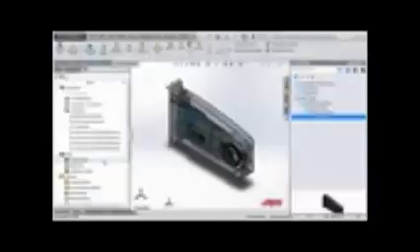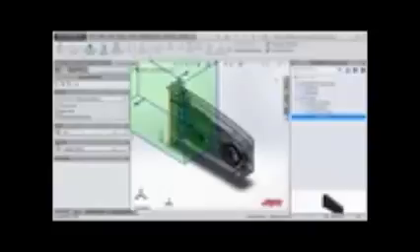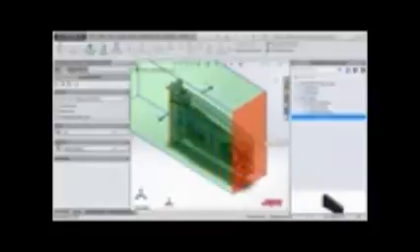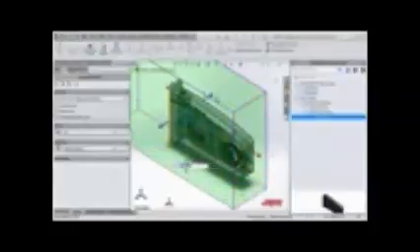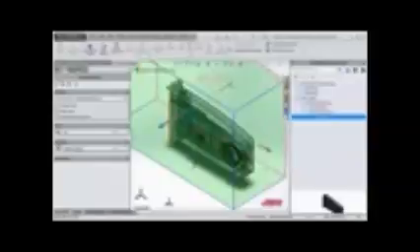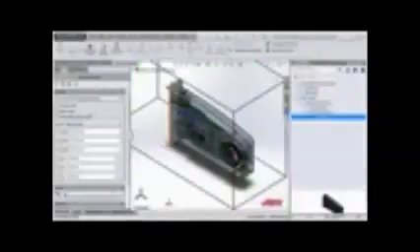We'll go to Overall Domain and change the domain type from internal only to internal and external. We now see dimensions for the overall size. We'll click on Edit in View, and as you can see, it allows you to drag the sides of the ambient and fit it around the model. Alternatively, you can type in the values, keeping the mode as start and size.